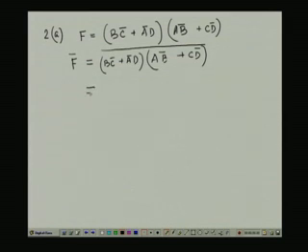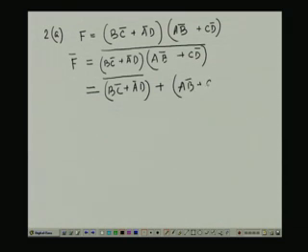So, the first part becomes the complement of (B C bar plus A bar D), this dot becomes plus, and then the complement of (A B bar plus C D bar). If we take this as the f1 function and this as f2, then f bar is f1 complement plus f2 complement.